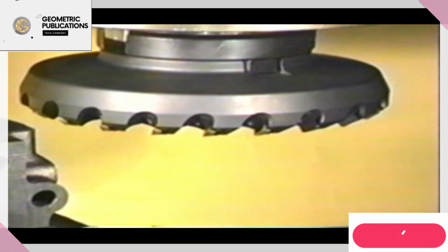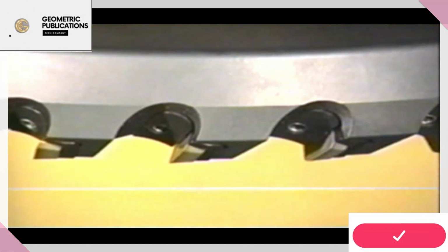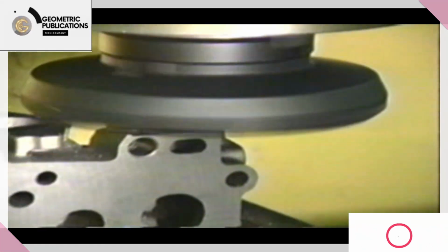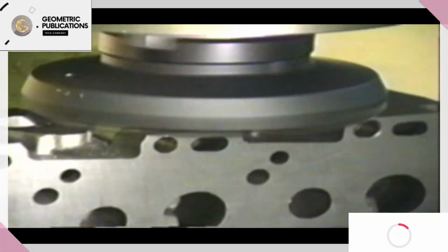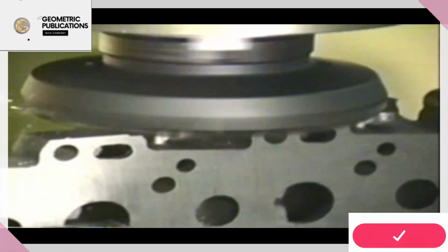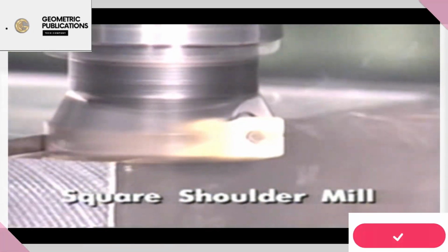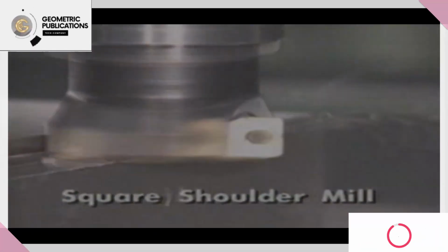In face milling, the cutter body has multiple pockets to accept a variety of insert types. Metal is removed by the peripheral edge of the insert, and its bottom edge cleans up the work surface and produces the surface finish. Some face mills, called square shoulder mills, generate a finished milled shoulder that is square to the face they mill.